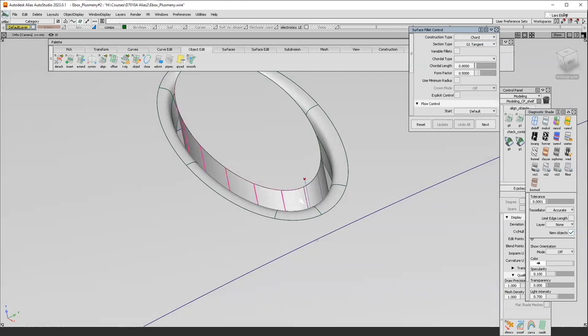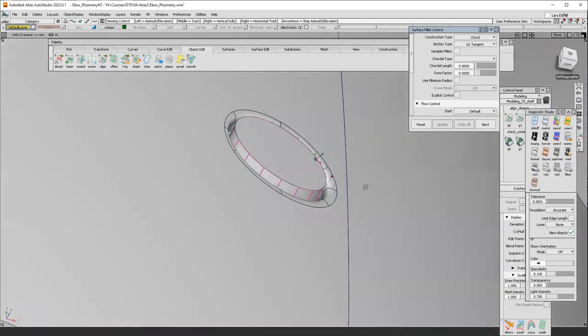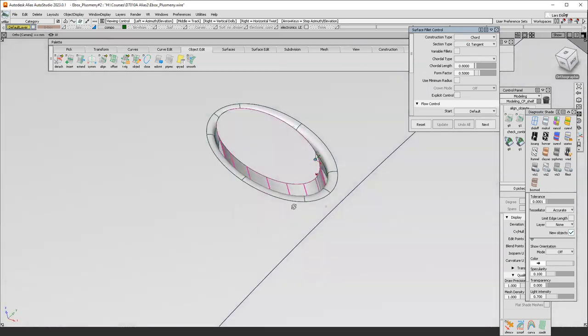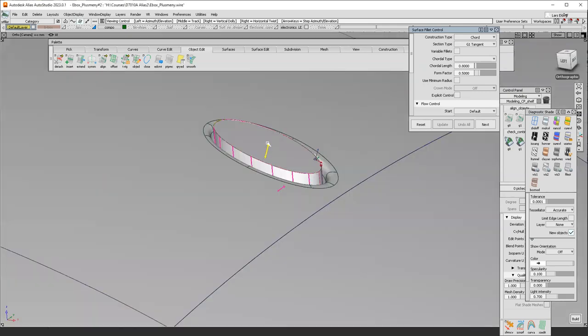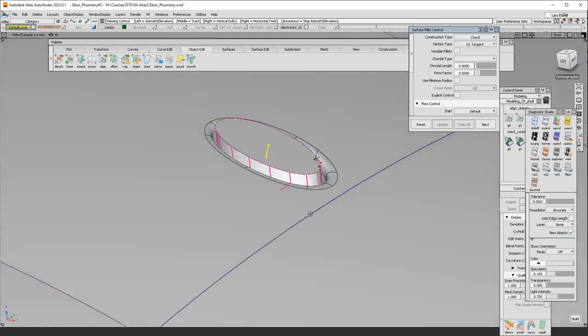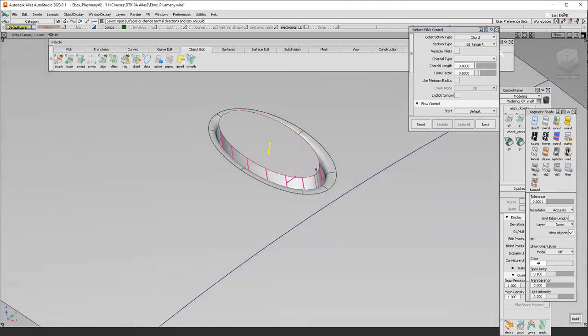I hit the walls first, which are pink or turn pink, and then I hit the top surface. Make sure the arrows are pointing into the center of our radius. And set that to either, we can check the difference. So radius, center radius 0.35. No, we probably want that a good 0.8 or something.